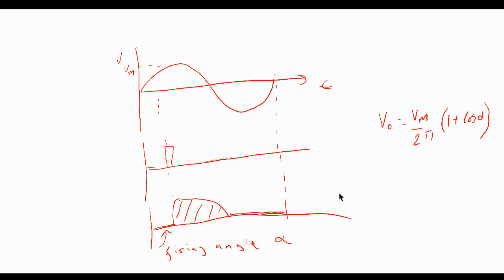Yeah, sure. Based on the diagram, after the pulse, the SCR conducts for the first half cycle. It would go off on the negative part of the cycle. You would need to fire it again for the next cycle.